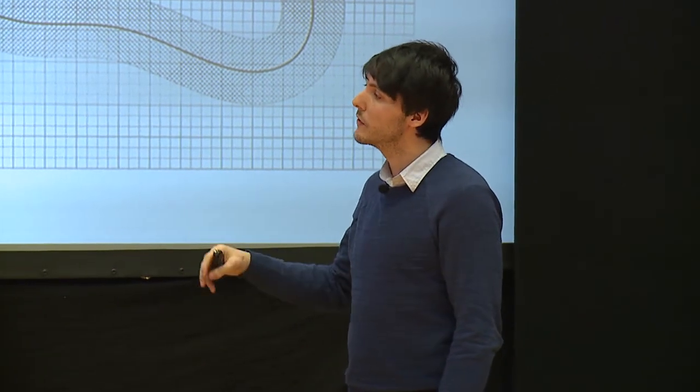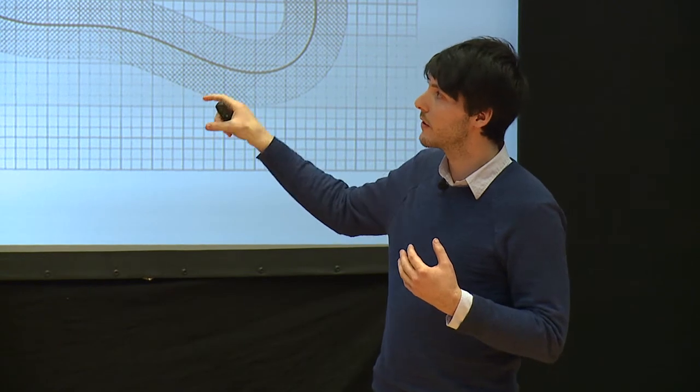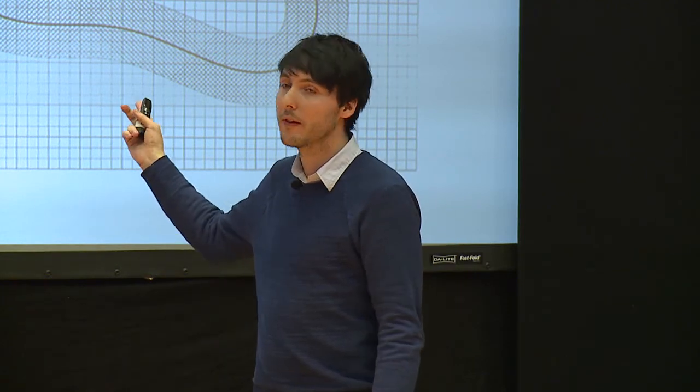But with the graph alone, it's pretty hard to visualize and see what the structure is. So the way we can take that graph and extract the shape and make something that you can see and model with is through this volumetric representation. The volumetric representation we happen to be using is a narrowband level set, which is like a distance field within a range of the surface. And we can go between these two representations pretty easily. We can also go from the narrowband level set to a mesh or a boundary representation if you needed to interface with other programs.